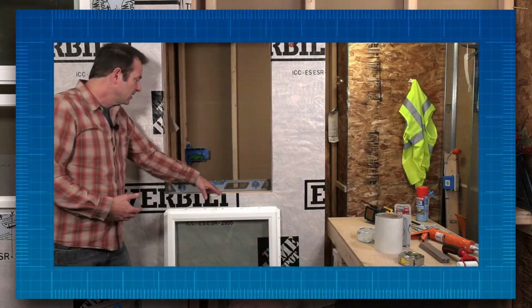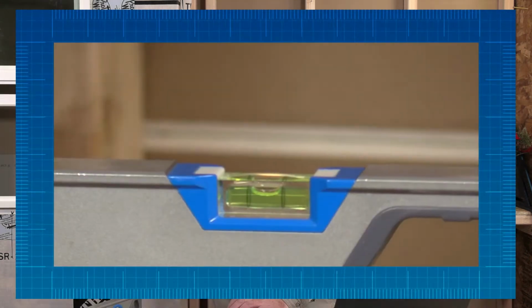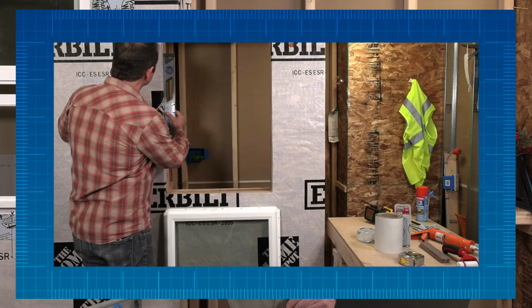Our third condition for that rough opening is how level and plumb is it. Our base or our bottom of our rough opening should be level, and our sides should be plumb. The top should be level as well. And if it's square and the sill is level, chances are all the other sides will work. It does not hurt to check these things though. So if you're on site, you have a question, have a level with you. It's an easy and quick check. It doesn't have to be a super long level, just to get a baseline check on it.